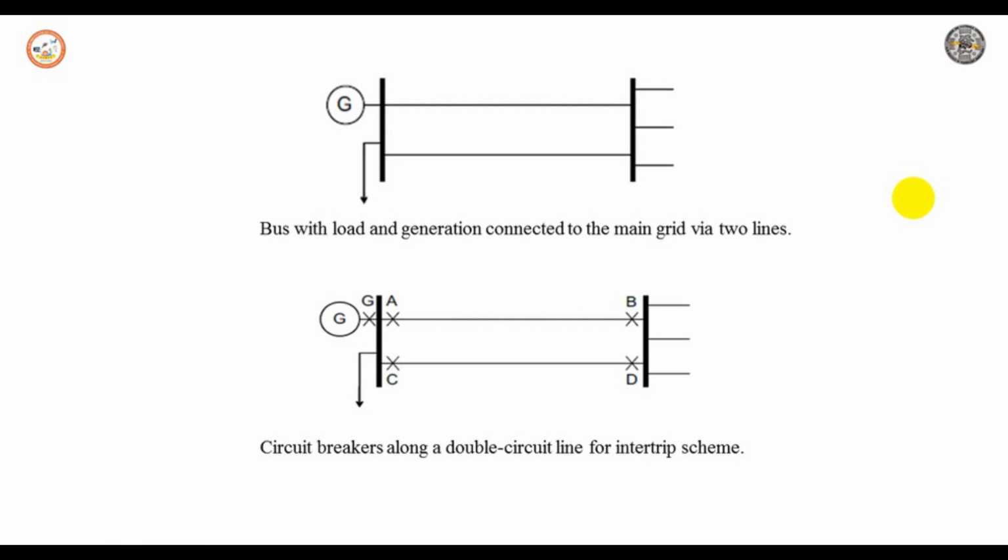So whenever one of the breakers A, B, C, D is tripped, the trip at G will follow. This is again a contingency experienced by our network operators. In this way, the whole transport capacity of the double circuit line can be used, without risking overload when one of the two lines trips.